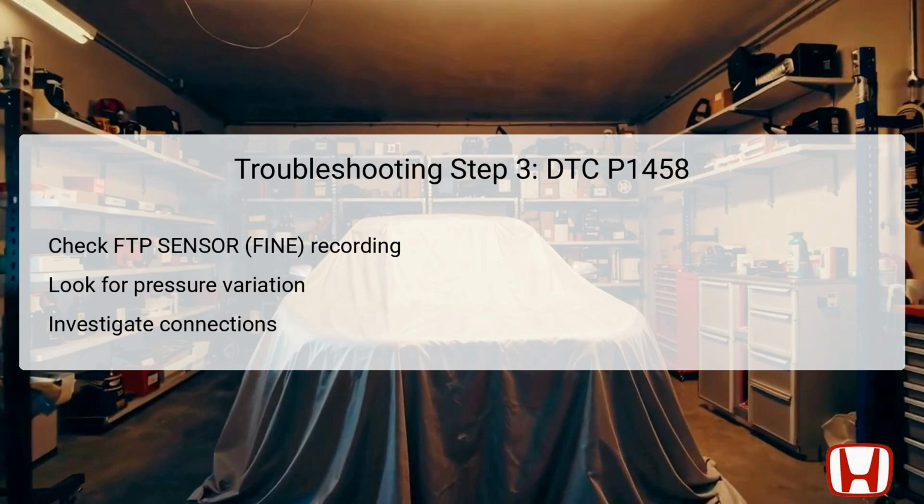If such variability is observed, it suggests that the sensor is functioning correctly, and the technician can proceed to the next step. Conversely, if the variation is insufficient, it points to an intermittent failure, which may indicate that the system is operating well at the moment. Hence, checking for poor connections or loose terminals at both the FTP sensor and related components is crucial. Additionally, blockages in the EVAP vent hose must be investigated, as they could be impacting sensor functionality and leading to P1458 detection.